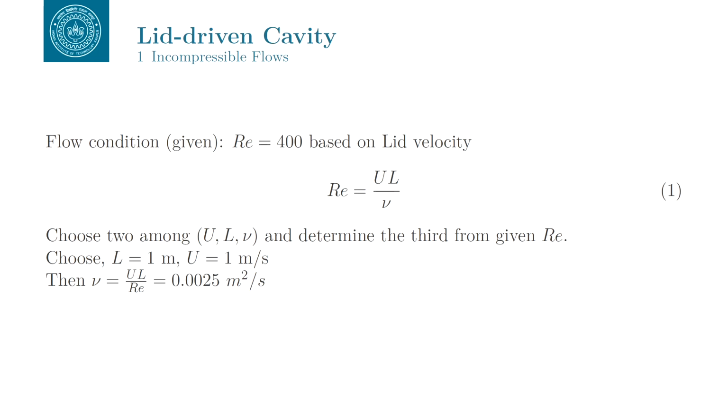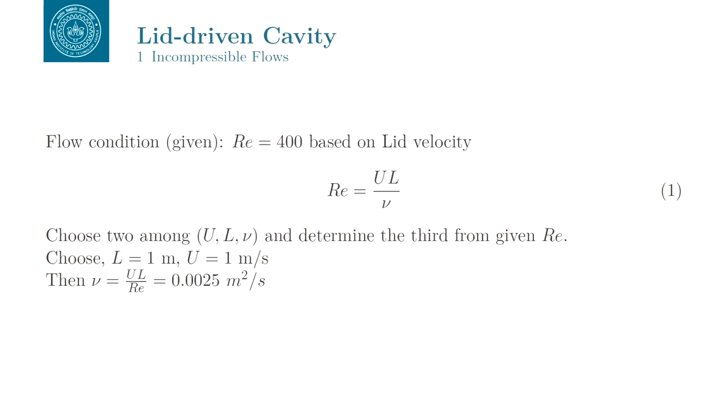So, you can take that P to be 1, P to be 0, or any value, it will not matter. The one thing you must note, in the case of OpenFOAM, in incompressible flows, you do not give the value P, but rather you give the value of P by rho. In compressible flow, you will have P, which is the thermodynamic pressure, whose unit is Pascal, or here you will have the quantity which is P by rho.